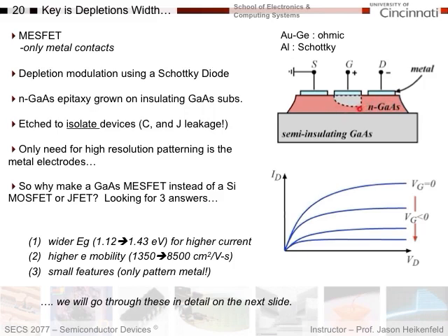And so what I need to do further, if I make devices, is grow this layer, but then etch the sides away, so that a device here won't cause current interference with the device over here or a device over here. They'll basically be isolated where I etched it out. So this allows me to have current flow just through this device. I can wire to the next device over here, but I'll have air in between, and the substrate doesn't matter because it's insulating as well.